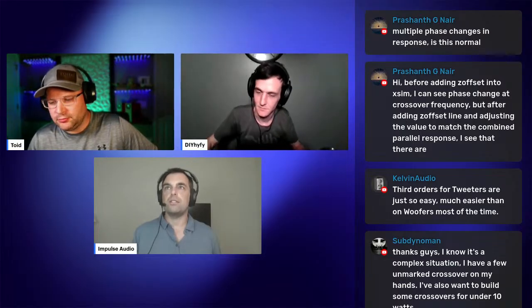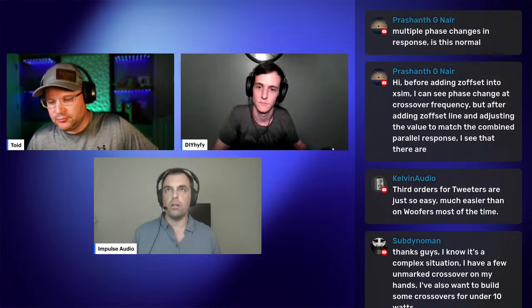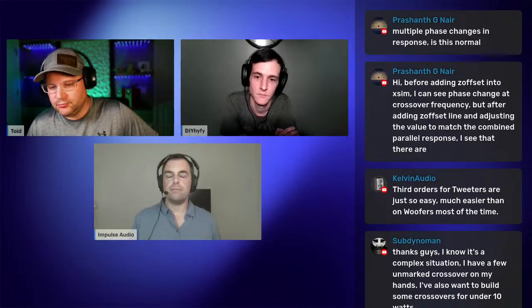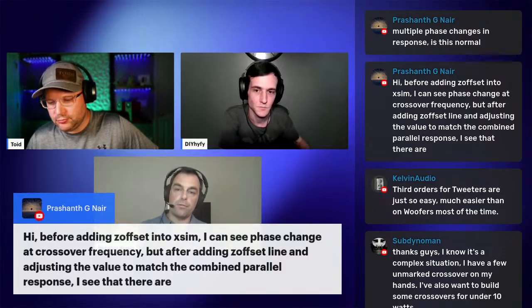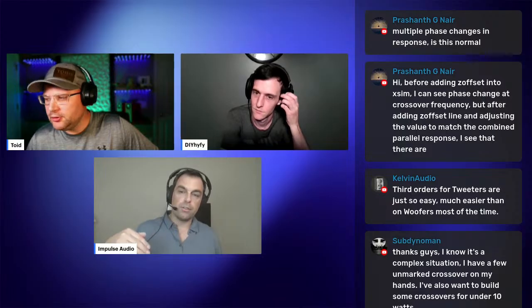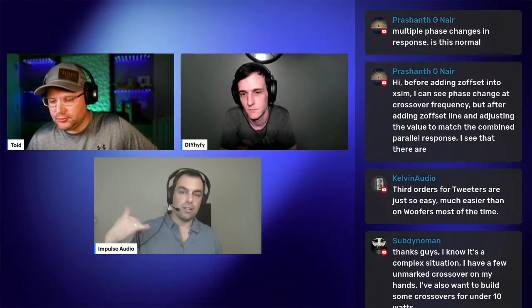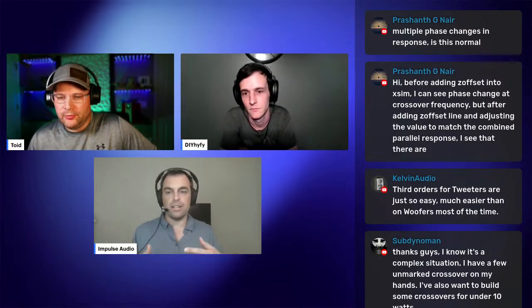I'm having a brain fart, but it's 45 degrees per pole. Am I right? So if you have a second order filter on your tweeter, that's 90 degrees of phase shift. So 45 per component. If you put a second order filter on your woofer, that's 90 degrees of phase shift in the opposite direction. So total is 180.